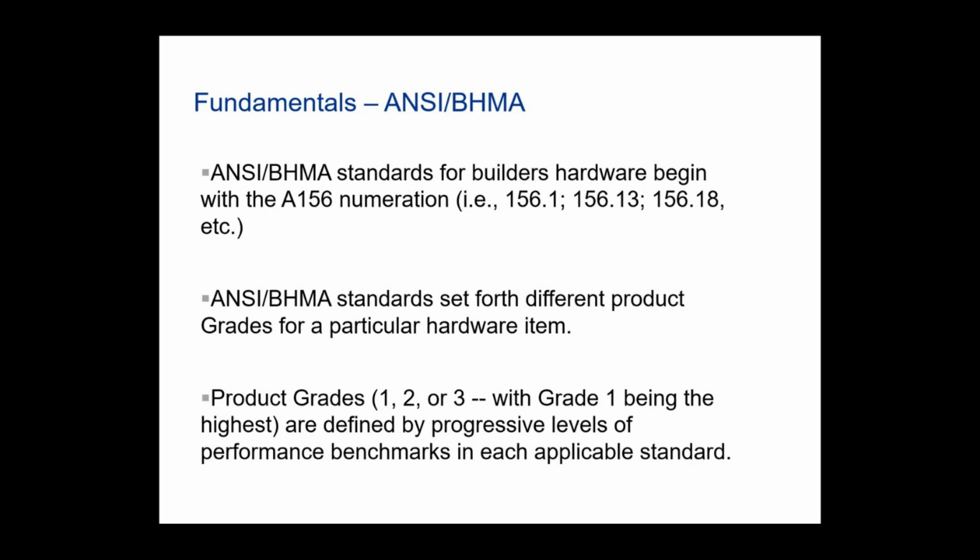And then you have one from Best Manufacturing or dormakaba that can go upward of 20 million cycles. So depending on what you're looking for, just because a product is grade 1 doesn't mean that it's superior to another. You might want to check what their cycle test is prior to breakdown, and what your usage is going to be when identifying what product you need for your building.